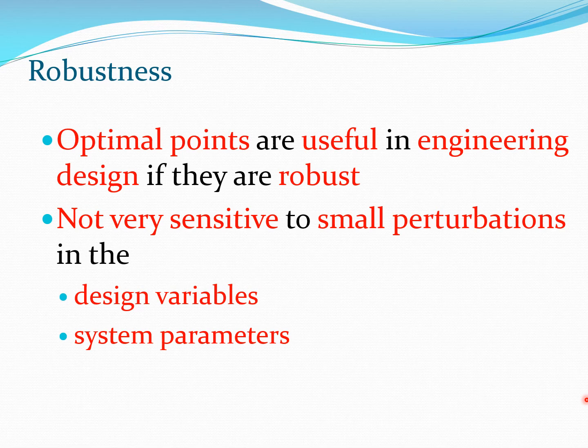Now again, you can formally address some of these issues in robust design, so we are not going to really look at the concept of RDO and RBDO here, where you actually use not only the objective function, but you also try to minimize the standard deviation corresponding to the cost function for the problem. So again, that is a more rigorous way of doing this problem, but that also becomes computationally very expensive. And this kind of response surface method is a much less computationally expensive way to handle this robust design problem.